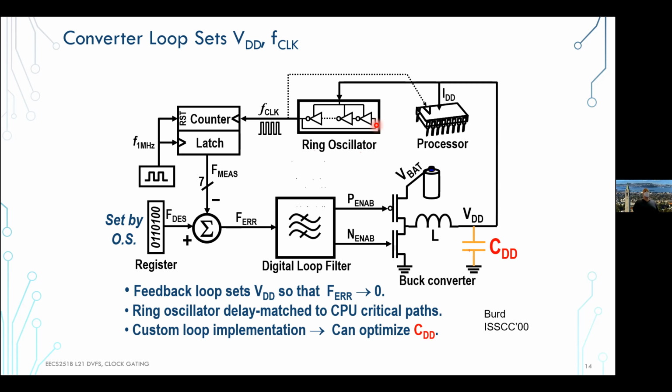So people try to make this more sophisticated, but this is basically the basic mechanism if you wanted a complete control loop that does this DVFS. Of course, we'll see that in reality, things are a lot more complex. You need to figure out where this thing is coming from. There are a lot more complex problems behind deciding what this desired frequency needs to be, and also what actually runs on this processor. This is not just a discrete IC; it could be multiple cores on the same chip, different domains. How do you allocate tasks between these cores, threads, and things like that? So we're going to talk a little bit more about that as well.